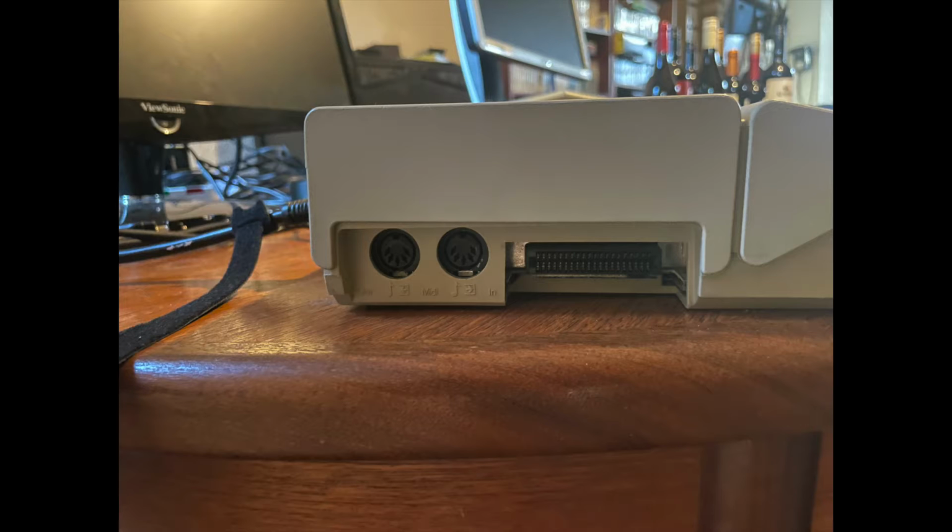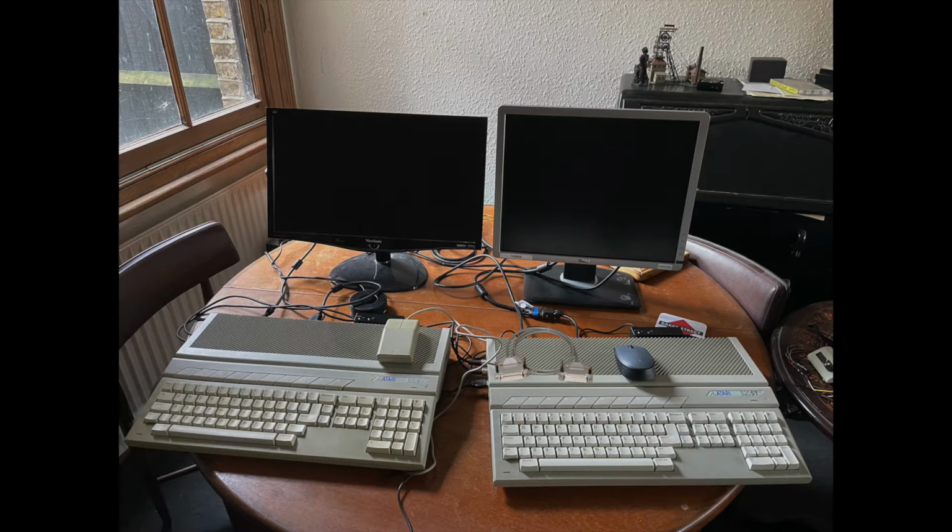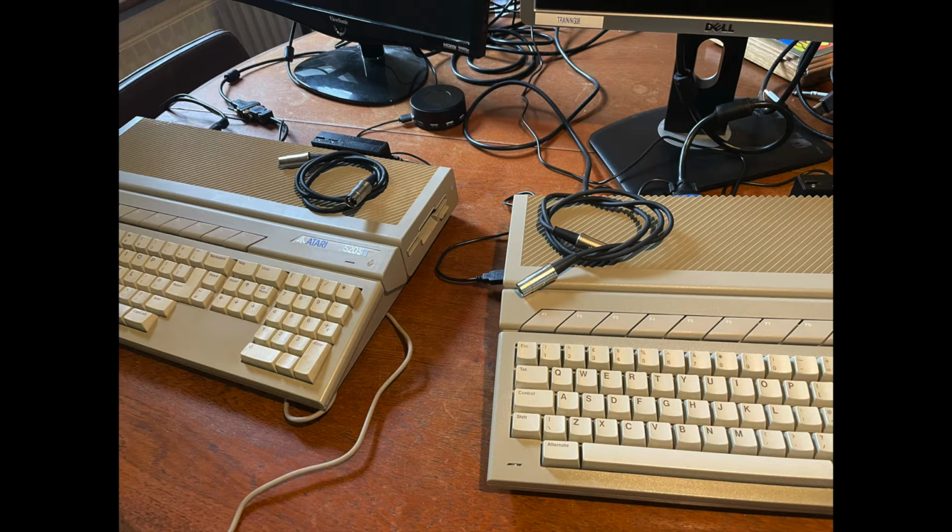Both of these solutions require buying or building cables. Serial data transfer requires one special purpose cable. That's called a null modem cable, which is really only useful for one thing, and that's data transfer. MIDI operation requires two cables. But unlike serial, these cables are useful for more than just data transfer. You can control synthesizers, drum machines, edit patches, sync with SMPTE, and much, much more. Extra equipment may be required.